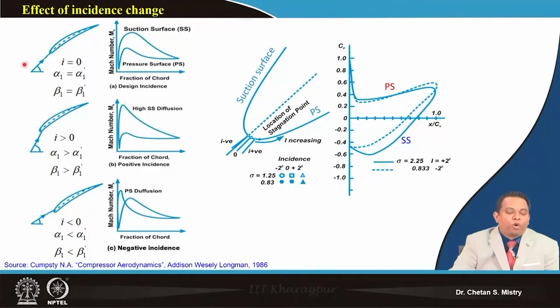So here, what we have learned from our fundamentals is that at the initial stage of my blade, near my leading edge, I will have flow acceleration, happening up to say 10 to 20% of my chord. So we will have a whole lot of acceleration happening on the suction surface. And in the later part, it is a diffusing passage, my passage area is diffusing, and my flow will get decelerated. So this represents the deceleration process, we can say the decrease of Mach number.